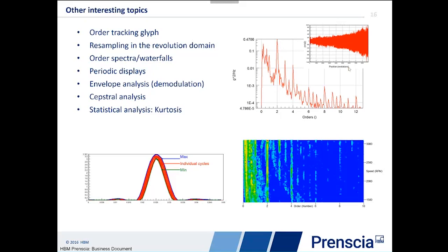So leakage-free, smearing-free spectrum. So that's probably the best thing to do. So you end up with those waterfalls here where the x-axis is no longer the frequency, but the order number. So order 2 is a vertical line, order 4, 6, etc. And that's probably the most precise, the best way to extract order slices, I think.